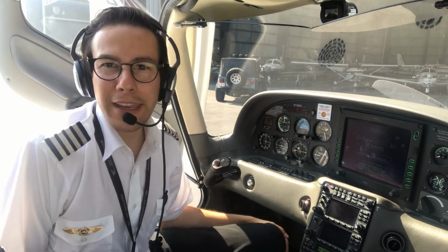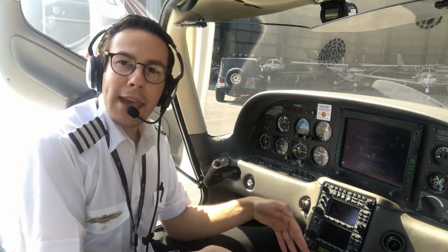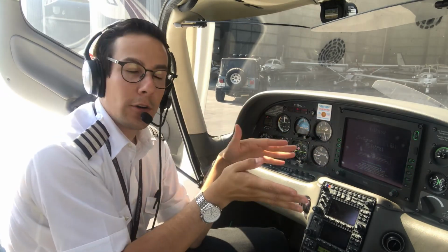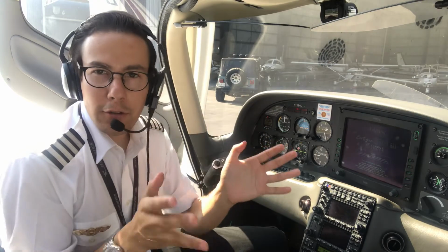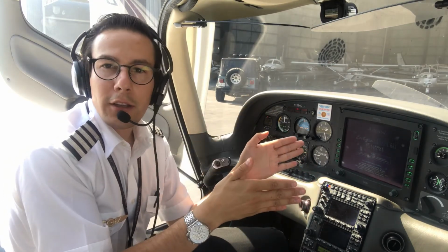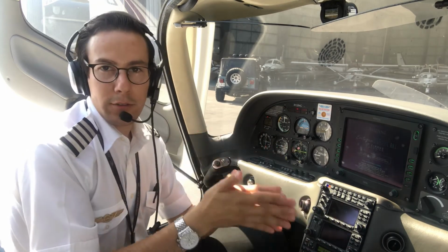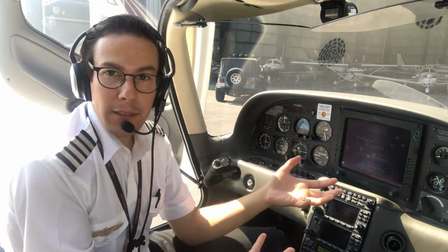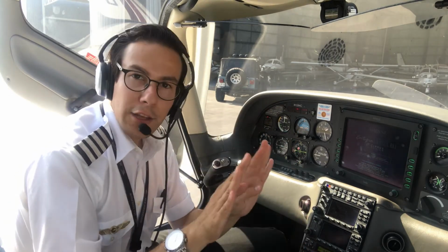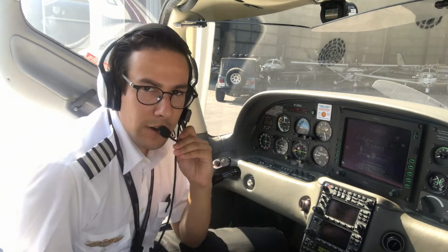Okay, very good. So today you learned the relationship between the fuel, the mixture, and the exhaust gas temperatures in order to get the best economy or the best power configuration for whatever we want. The best power, we're gonna get more power, but more fuel consumption and more speed. On the best economy, we'll have less fuel consumption, less power, and a little bit less speed, but we will increase the range.